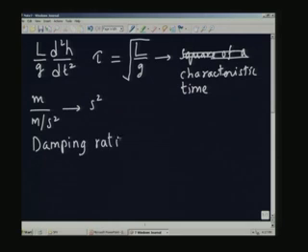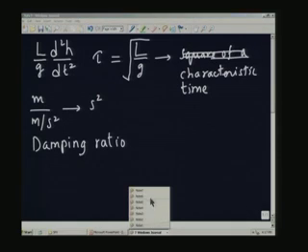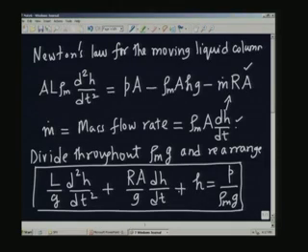In applied mechanics, you would have come across the vibration problem. You would have come across an equation similar to this. This is actually the vibration of a damped system, spring mass system with damping. The first term is the acceleration term, the second term, which is proportional to the velocity dh by dt, is the damping term, and the damping comes because of the viscosity. In this particular case, laminar viscous flow will give rise to a linear damping, and then the third term here is the displacement, and the spring constant is going to come here.